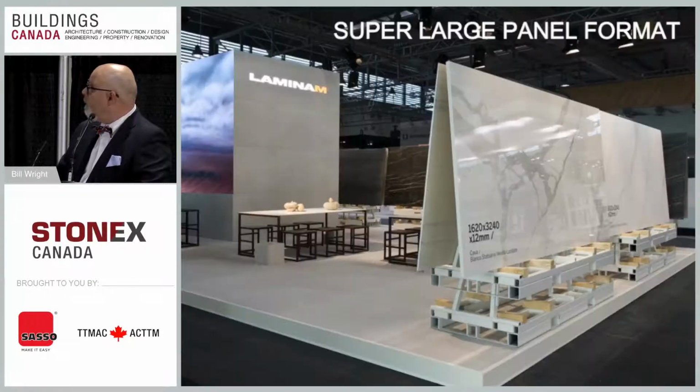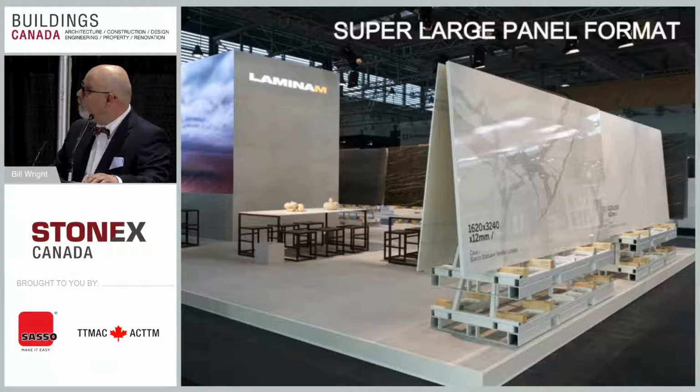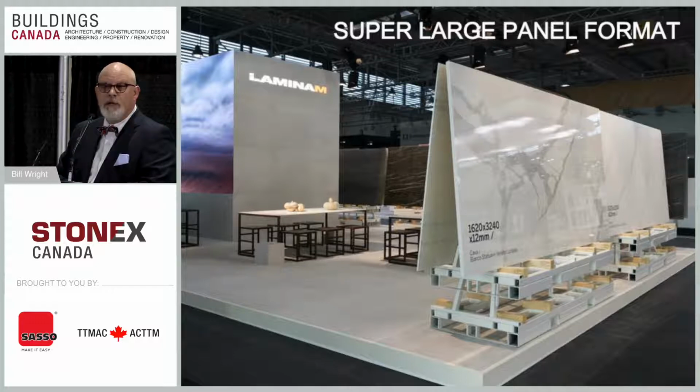Okay. Now we have super large format porcelain tiles. These require a lot more prepping, a lot more care taken in terms of the flatness. Many of the manufacturers of these types of panels have installation recommendations. Get them from your suppliers and include them in your specifications so that there's information available to the installer to make sure that he has the proper types of trowels. We want a different type of trowel than traditionally used. We want different types of mortars than traditionally used. So get the manufacturer's installation instructions and certainly pass those on in your specification.